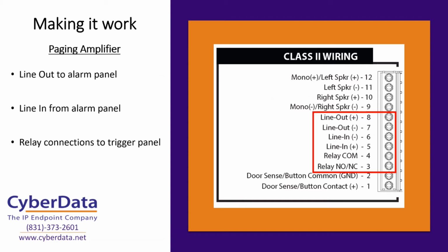And again, that would be the actual terminals to go and activate the fire panel system. So you'd call the paging amplifier, enter whatever DTMF code is necessary, it would trigger the onboard relay, and then the fire panel can work its magic. So that's how you would actually make these connections work, and the actual pinouts that would be used for these two different applications.